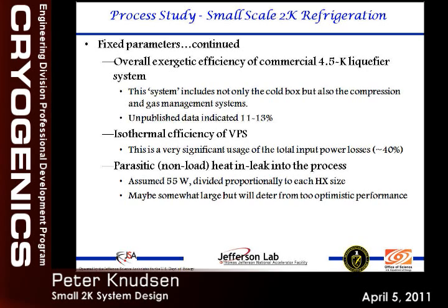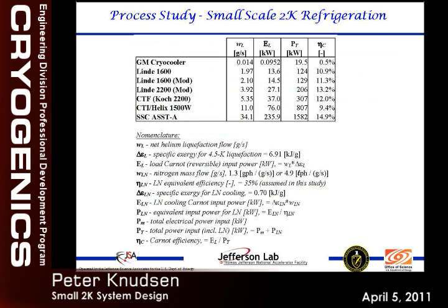Also, a fixed parameter is the isothermal efficiency of the vacuum pumping system. It is not very well understood how this varies with the pressure ratio, but based on the data that we have from CTF, this is how we arrived at what we believe it should be, at least for our study. And for the parasitic heat leak into the process, we assume 55 watts, just to be conservative, to not get too unrealistic numbers. So again, those are fixed parameters.